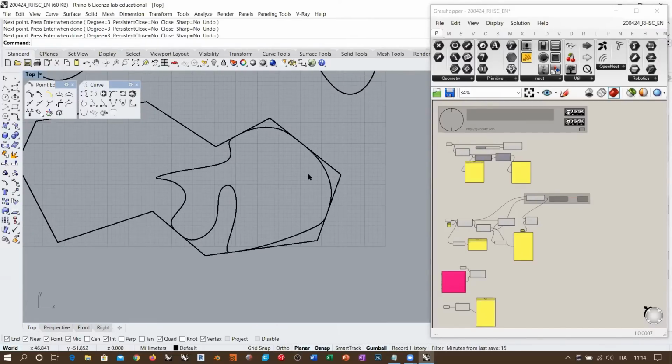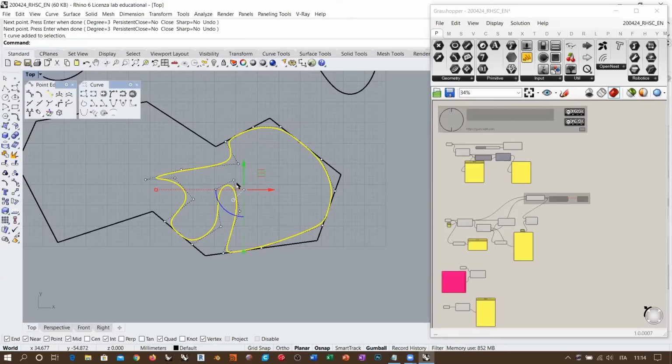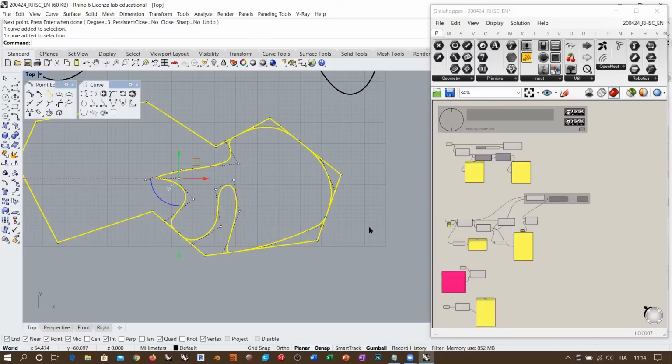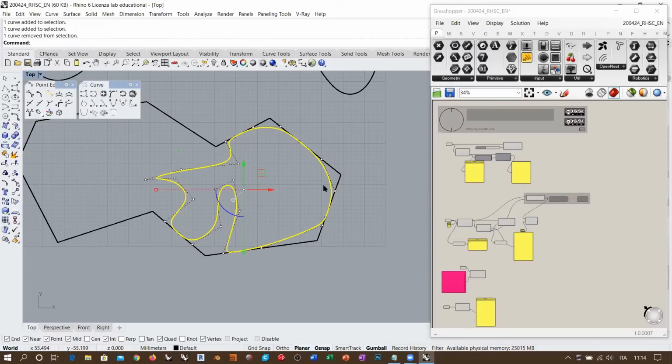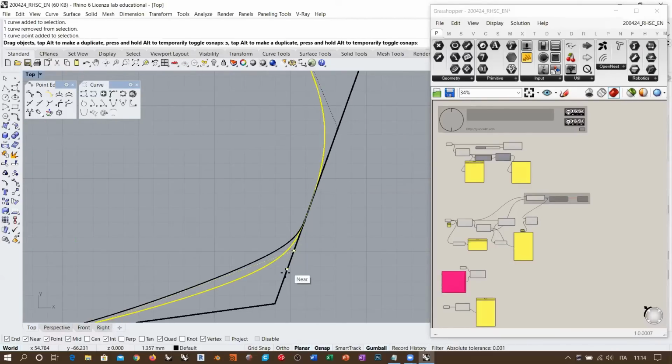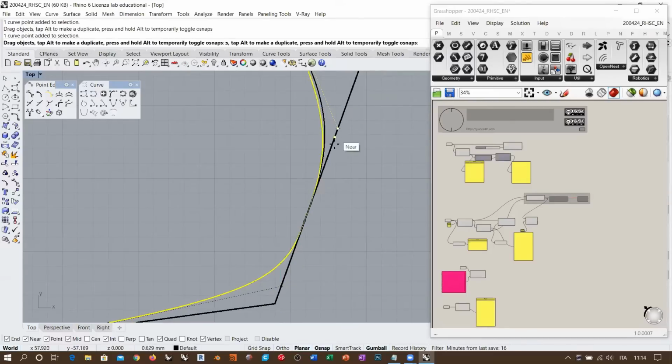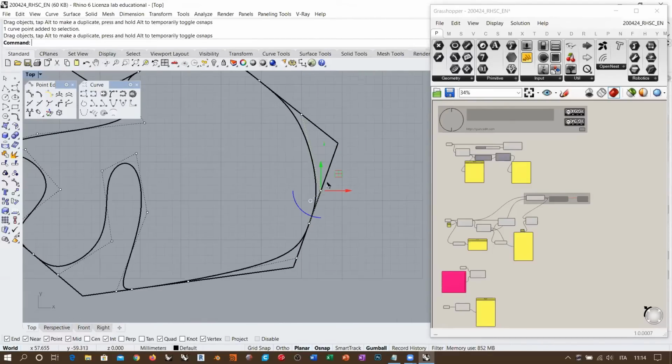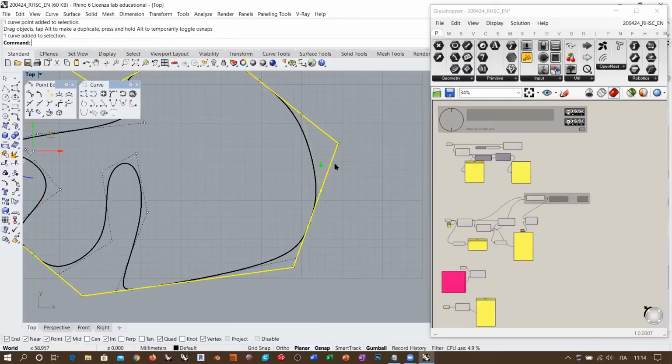What's the advantage of doing this is that if I take this control point curve and I click on it with Rhino 6, I already have the visibility of the control points, okay? And so I can edit the shape of this curve because I have created the necessary topology in order to have a curve tangent to this perimeter here, okay? So the control points are placed exactly in a way that allows this curve to be tangent to the outline. So if I take this control point here, I know that if I move this control point along this edge, I am not breaking the tangency between the curve and the line, okay? Because I am always keeping the 3 control points aligned along this edge, okay?